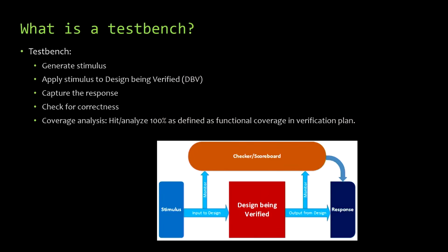Well, the standard way is to use a simulation test bench. And what's shown here is you're going to have your hardware design. So this is your Verilog code. That's the block in red. And you're first going to have some way of generating stimulus into that design. The typical ways that happens is either what's called directed testing or random testing.